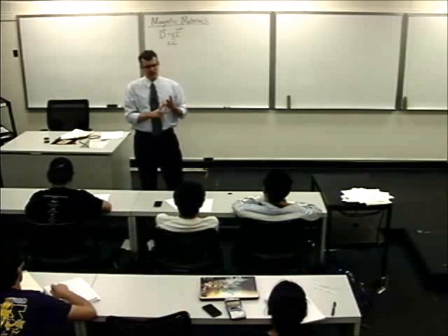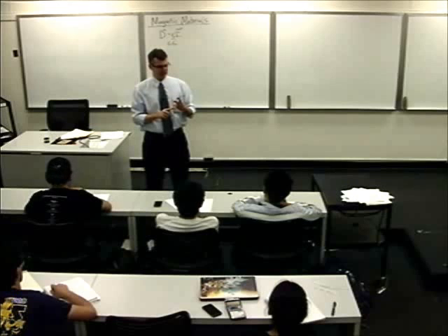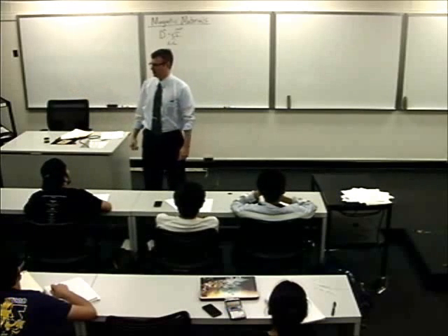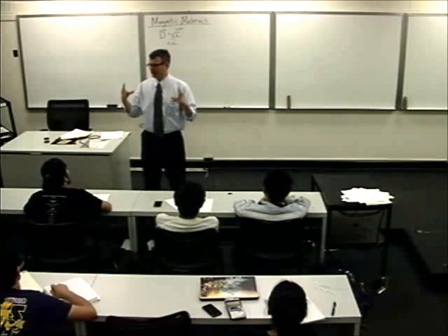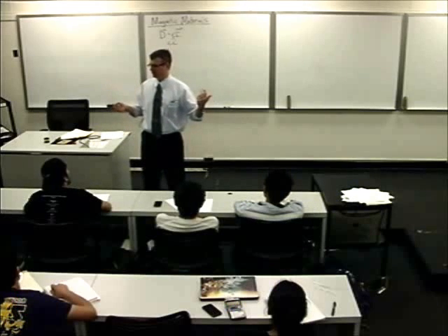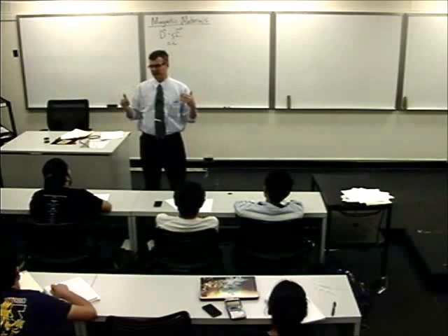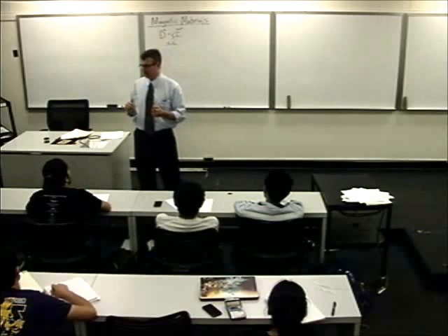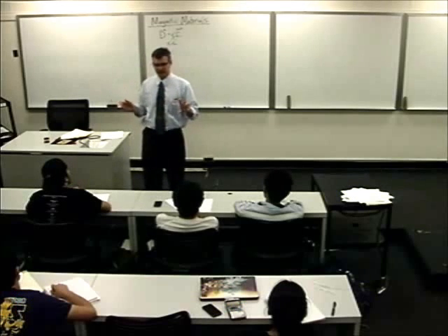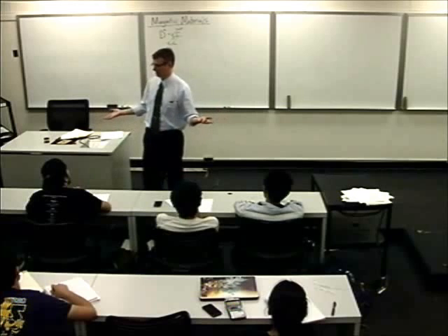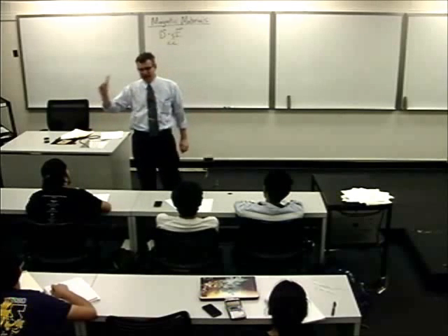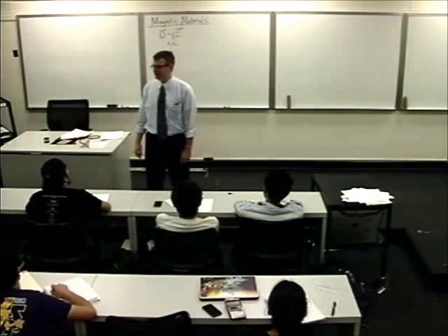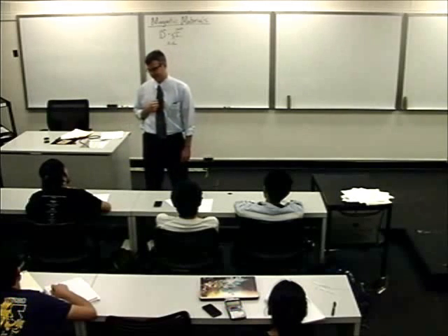And the other thing is that the range of permeabilities is so dramatic compared to epsilon sub r. Epsilon r is always greater than 1. If you have a solid piece of material, it's usually a single-digit number, a solid dielectric. You can engineer materials so that they have epsilon r's in the 10s or even the 100s, and that's a pretty impressive feat. Mu sub r at certain frequencies can be enormous, in the tens of thousands for certain types of materials. And yet, most materials, their magnetic behavior is minuscule. Very hard to even measure the difference between that and free space.